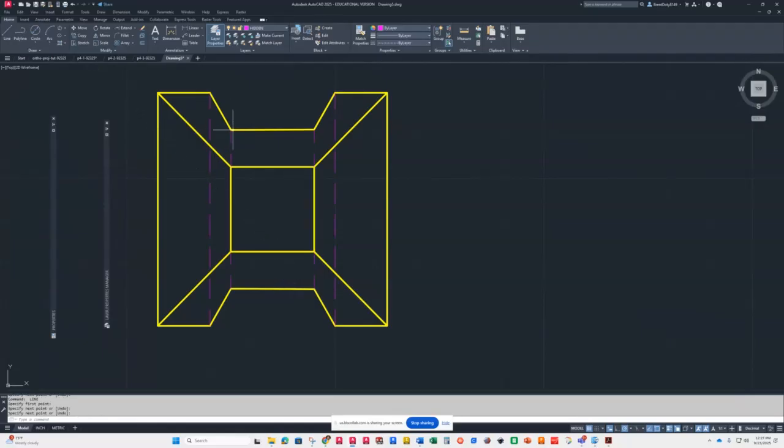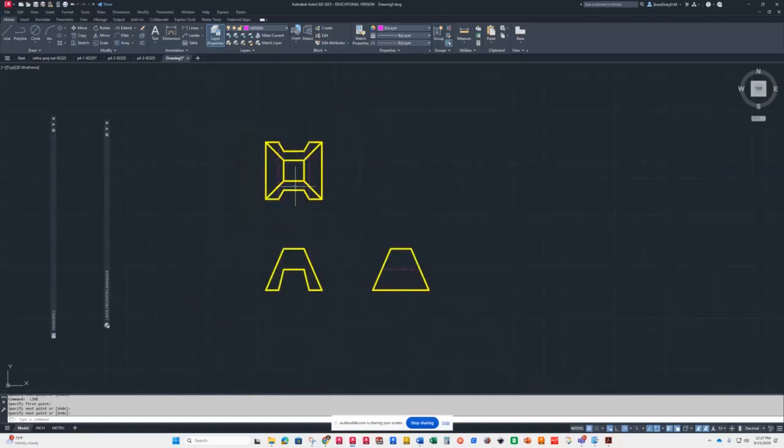Now, if you draw it from here down to here, make sure you trim out the hidden line underneath this solid line, because you don't overlap lines. You don't cross the streams. Bad things happen when you cross the streams. So don't cross or overlap the lines. Just ask Bill Murray. Okay. So we'll see how many people listen and didn't listen.